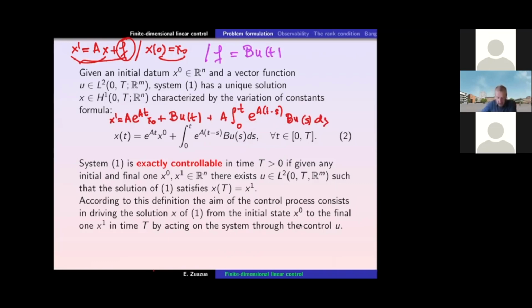So you see that this is a typical problem in which I'm solving the forced dynamical system, but the applied force F is not arbitrary, in particular because the range of the forces I can apply is always included in the range of the vector B. So out of all possible forces, I can only apply those that are realizable, accessible, doable through the control operator capital B, okay? But the formula for the solution, of course, out of the variation of constant formula applies.